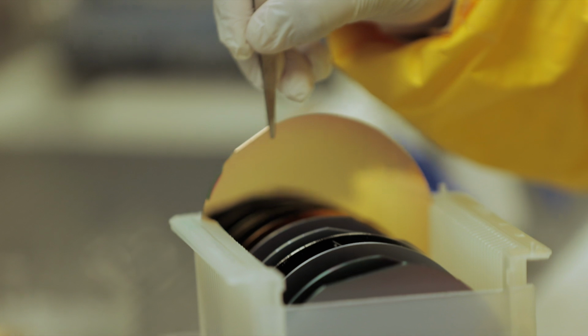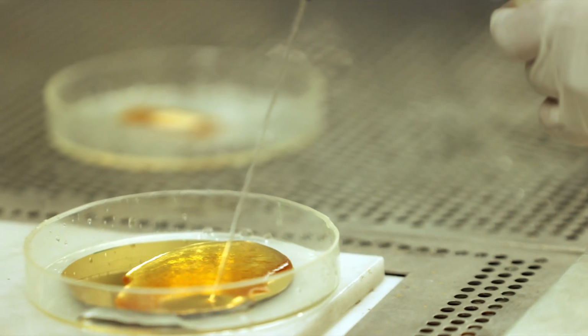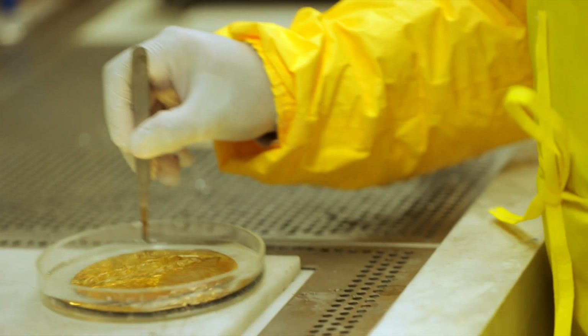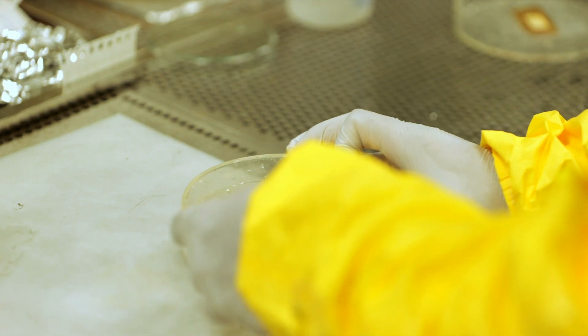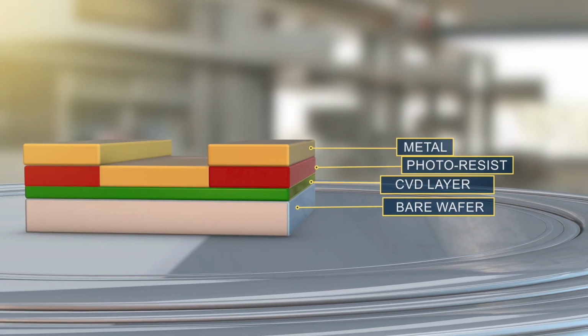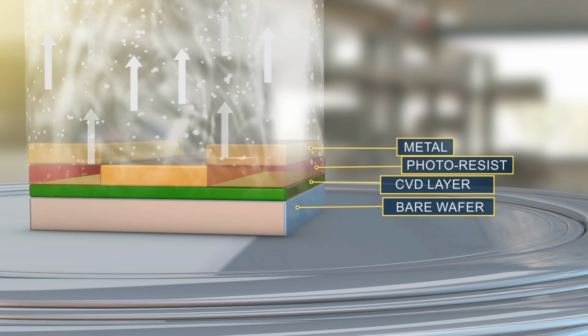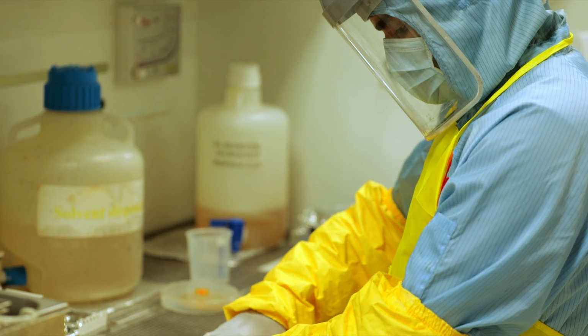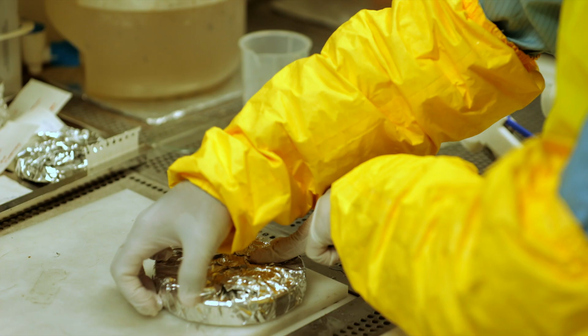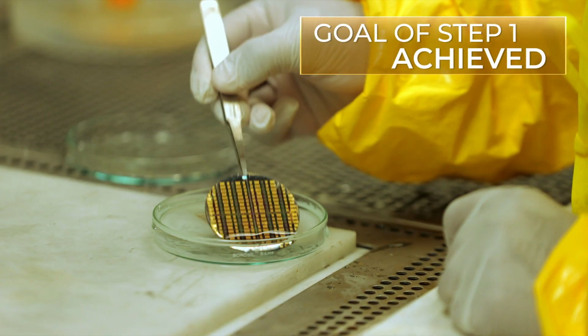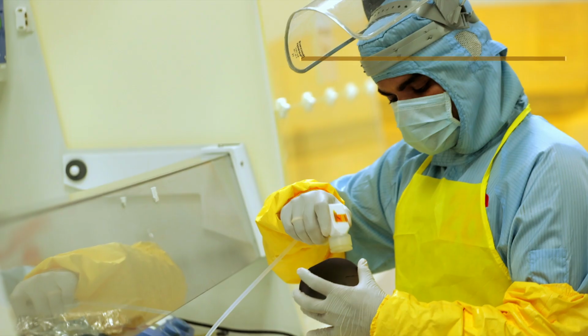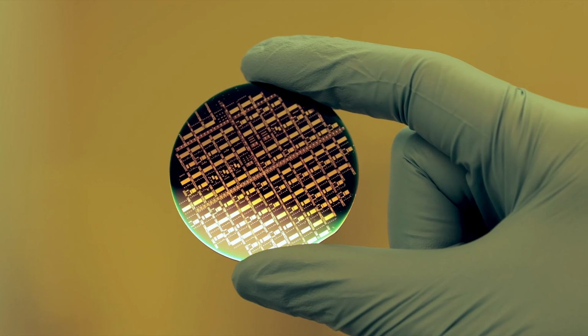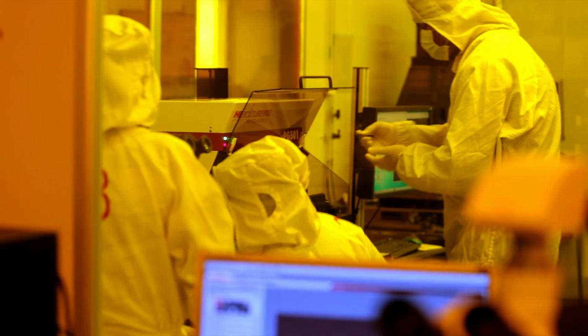The wafer is now subjected to a process called lift-off to get rid of the photoresist-coated metal. It is dipped in a solvent that dissolves the photoresist and in the process removes or lifts off the metal on top of it. The metal that is deposited on the wafer surface stays in the form of the pattern that was desired. The first mask step we had embarked on, what appears to be a long time ago, is now over.